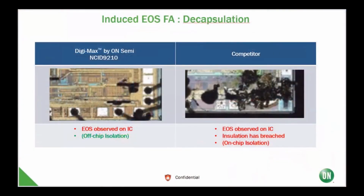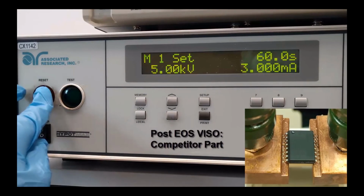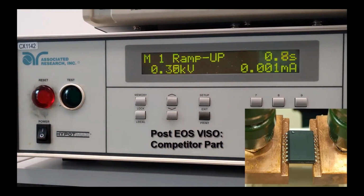Here is the resulting damage on the ICs. On the left is the ON Semiconductor Digi-Max isolator. On the right is the competitor's on-chip isolator. Both ICs are damaged. The parts were tested prior to decapsulation for the isolation specification VISO at 5,000 volts for 60 seconds. Here we see the competitor part fails at 2.76 kilovolts following the EOS event.